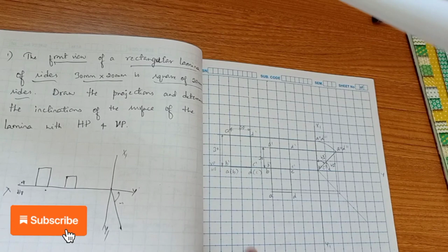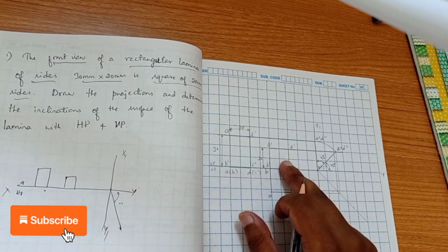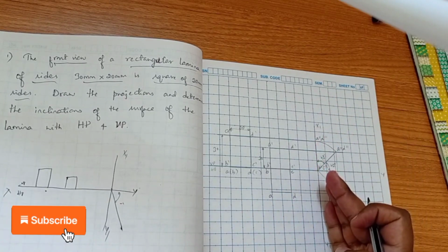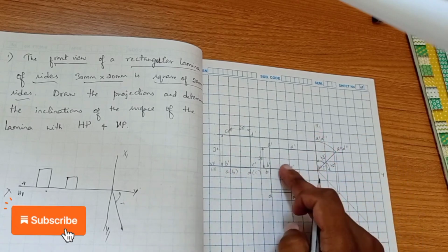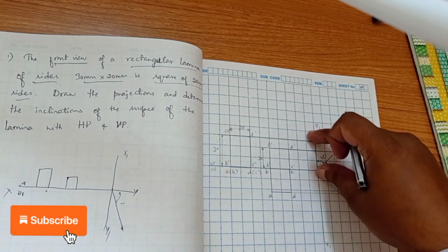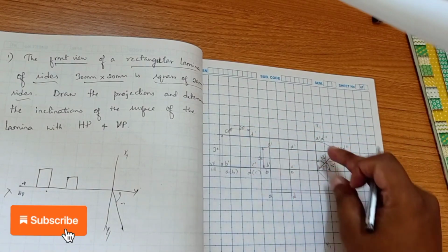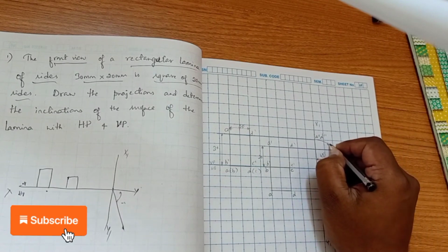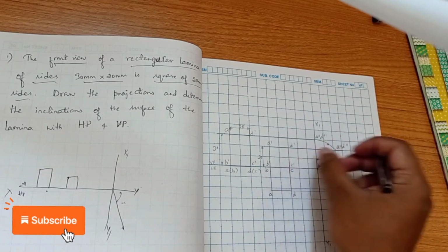So in this, first we drew this one and the top view. Second, after that we drew this one. Then we drew an x1 y1 line to draw the side views. The side view of this falls on the xy line, and the side view of this falls here. Because we are inclining it in such a manner that we get the top view, we incline it by means of an arc. Here I'll show the direction with the arrow mark. By inclining it, cutting the arc, we get the side view of this position.